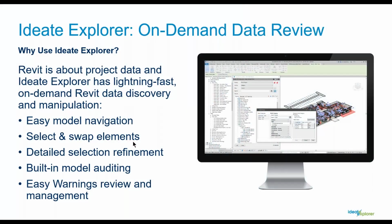Ideate Explorer, people have heard me say this probably multiple times. It's my favorite product. It's my way of navigating live and on demand through my entire Revit model. It's great to navigate, easy to select and swap elements. I can do detailed refinement of selections. I can say, I have a selection of certain categories here, but now I want to know a little bit more: who created, who last updated, are they pinned, are they in-place families, are they in model groups, which model group? That's the kind of information that Explorer can report to you.